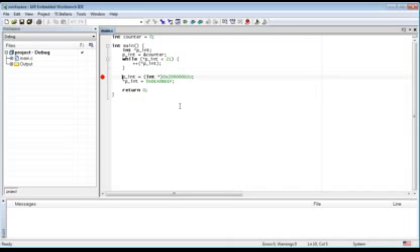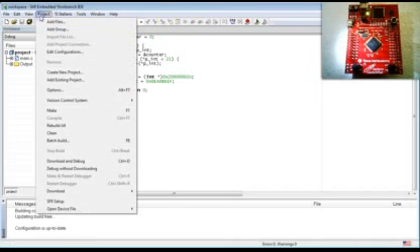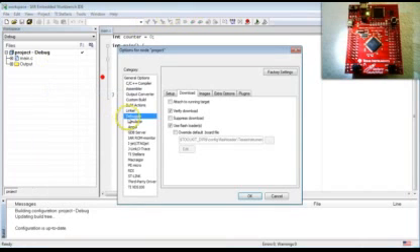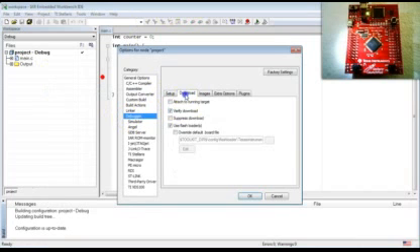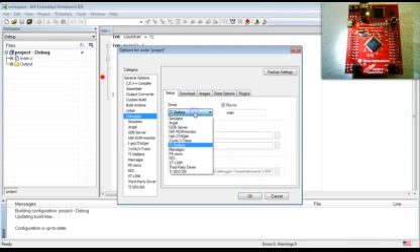If you don't have the IAR toolset, go back to Lesson 0. If you have the Launchpad board, you should connect it to your PC now and make sure that the debugger is configured for the TI Stellaris interface and that the Download tab has the Use Flash Loader option checked. If you don't have the board, configure the debugger for Simulator and follow along.